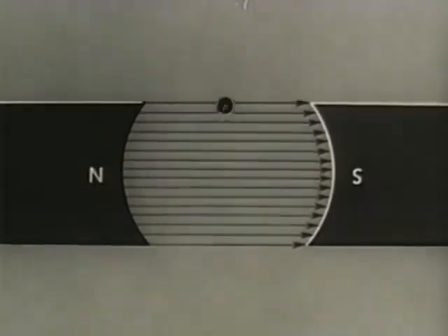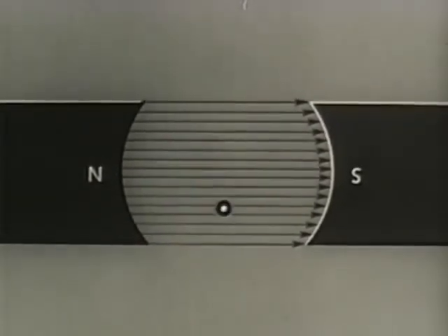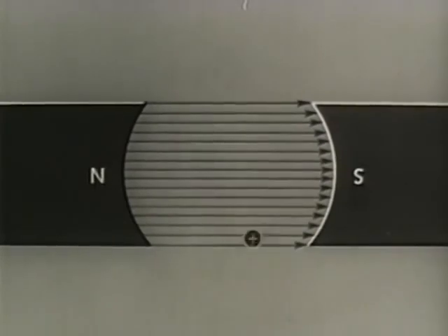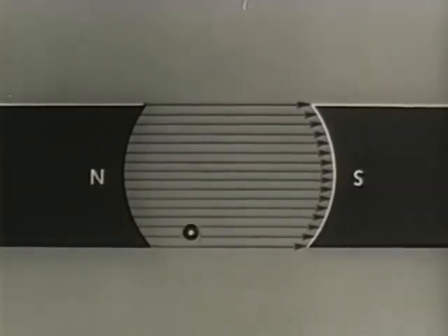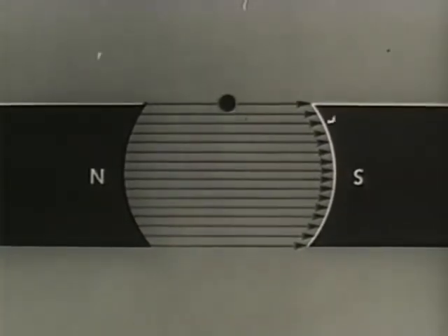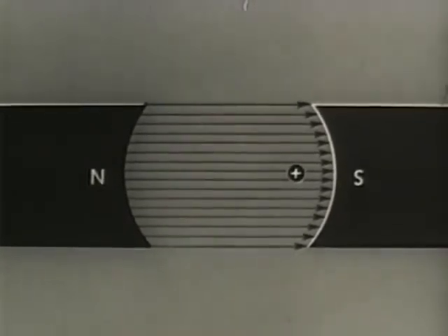But the conductor in an actual machine is not moving in a straight line, but rotating. When the conductor moves in a rotary path, the number of lines cut varies, depending on the position of the conductor. At the top of the field, for instance, no lines are being cut and no EMF is generated. As the conductor keeps turning, the number of lines cut increases, so that at a quarter turn, or 90 degrees, the maximum number is being cut and maximum EMF is generated.